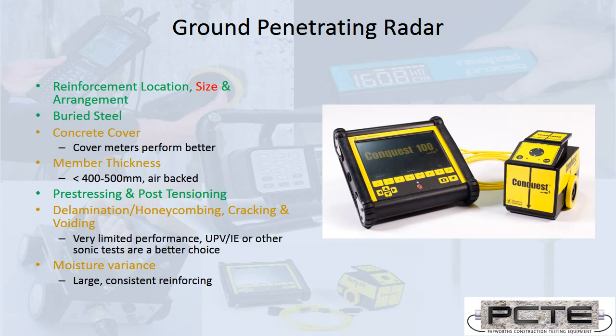So if we're measuring concrete cover with a GPR system versus measuring it with a cover meter, and we set it up as well as we can, we calibrate off a physically measured point, we might be within 1 centimeter uncertainty versus the 1 millimeter uncertainty of a cover meter.